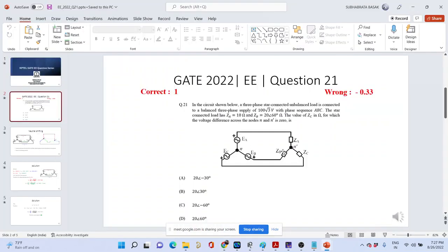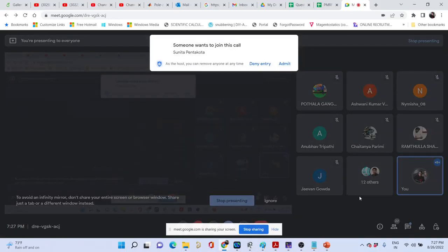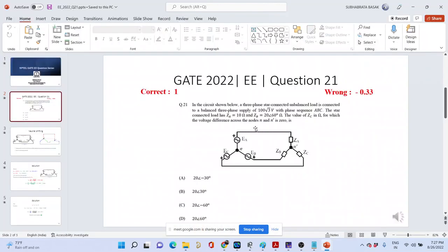Anyways, so yeah, the currents IA, IB and IC would be unbalanced. You are correct. So because of that, what problem are you going to face? What is the problem if I draw unbalanced current? Anyone? What problem can we face if the currents are unbalanced? So neutral current is not going to be zero. Absolutely. So this question itself gives you a very good example of oscillation of neutral. I hope if you have gone through machines, you have read about neutral oscillation when third harmonic current flows and all. But let's see what happens over here.